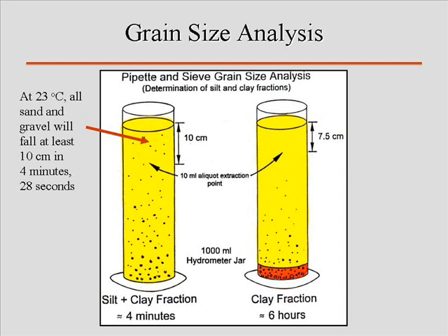Now, I've got a range of different things for you to use in terms of temperatures, but it's absolutely vital that the temperature in that room, the SED lab, is consistent. It might go up a little bit, it might go down a little bit. But if the temperature drops below about 19 degrees Celsius, you're not going to be able to do it. If it rises above 25 degrees Celsius, you're not going to be able to do it. So that's why we have to have a very strict temperature range.